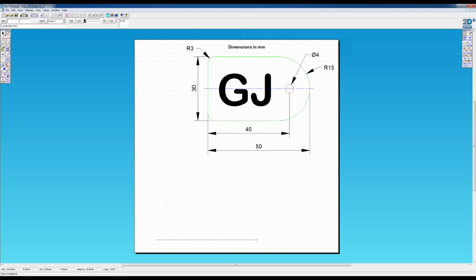Left click. Some people might prefer the other method, so we'll go through that again. Double click. The height's going to be 30 this time, with an angle of 90. Then we do another one, 50 by 180. Exactly the same as drawing a 0 degree line, but it will start at the right and go to the left. So we can drop it where we want it. And there's no need doing the last one because it should just be dot to dot, close the loop.